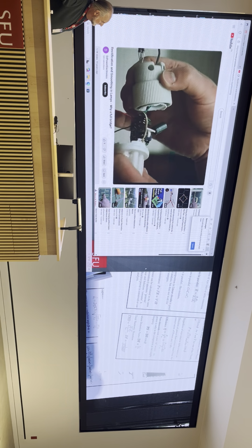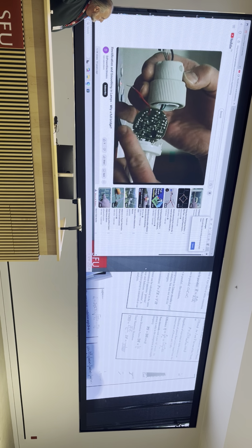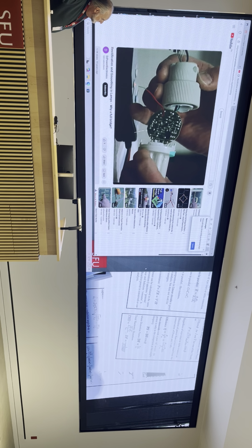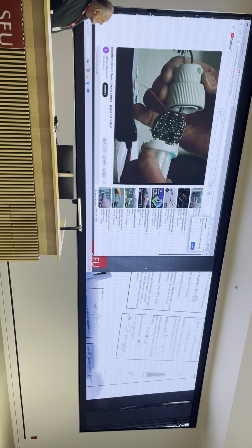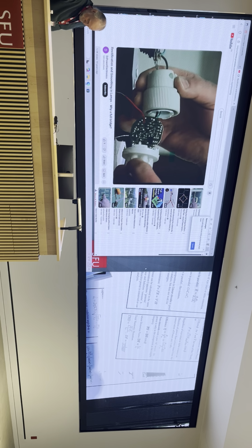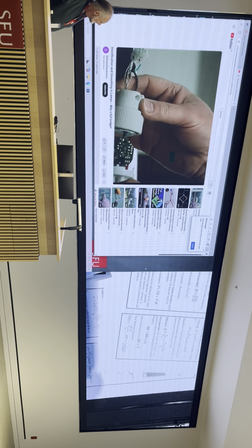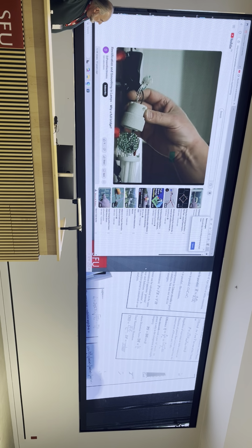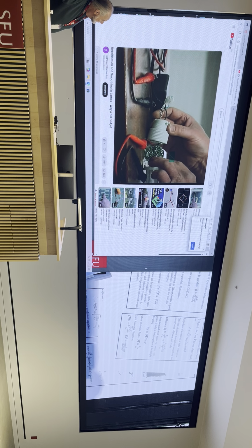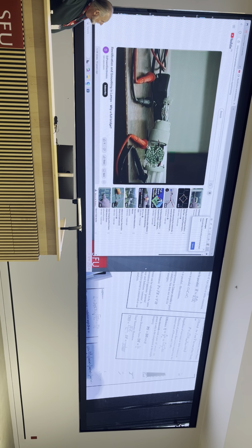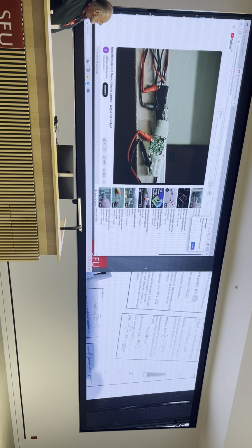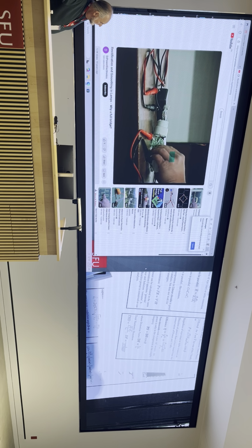So I've taken that to pieces. I brought in a couple of wires either side of that capacitor so I can connect to it. And we should be able to measure some voltage. And I've added some resistors here so we can measure the current of the main supply. So, just check that this is going to work.